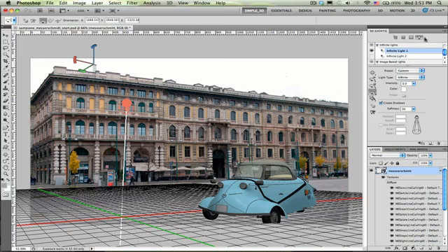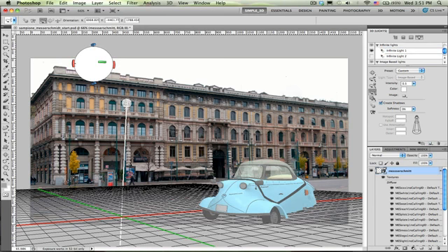So I'm going to choose in my 3D Lights panel at the bottom again, this middle menu, choose New Image-Based Light, and by default we actually take a white canvas or a white image and wrap it around my 3D object. That's why you can see this lighting up, and you can see that I've taken that canvas and essentially wrapped it around the scene. Okay, imagine my 3D object at the center of this axis, and this white light is wrapped around it.